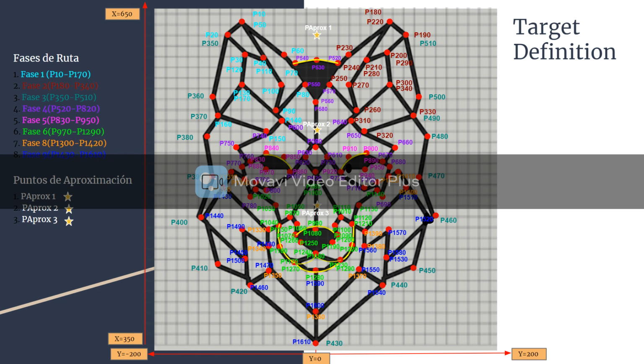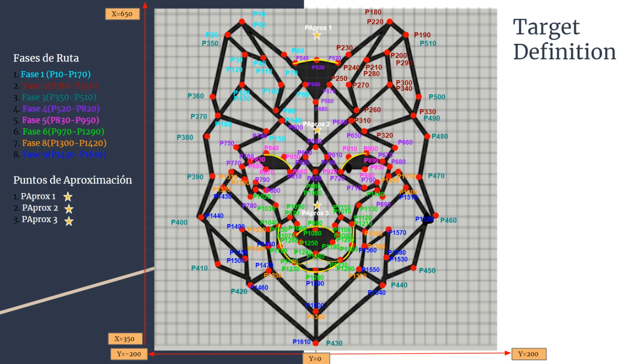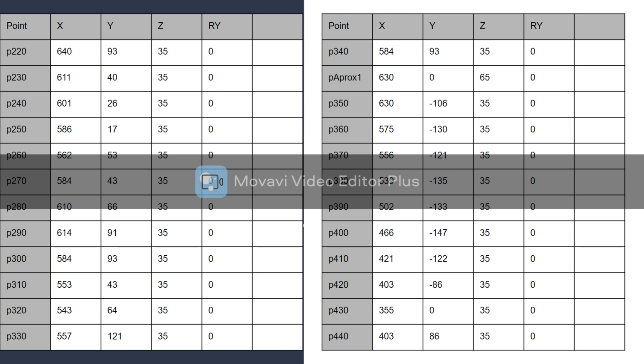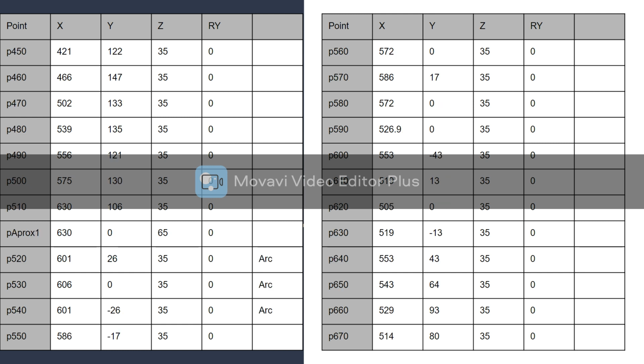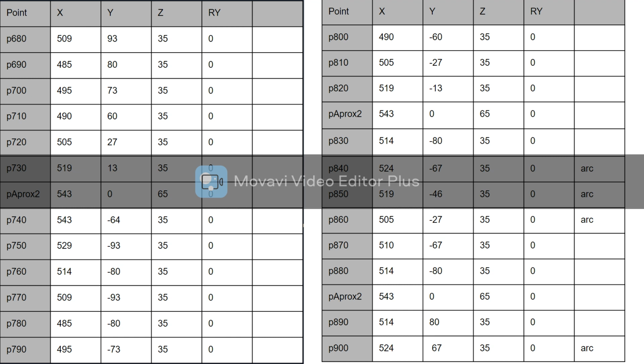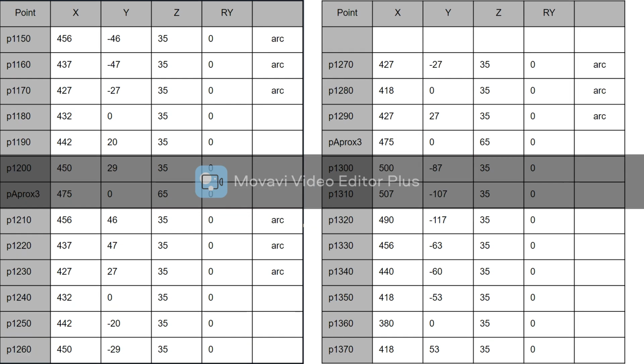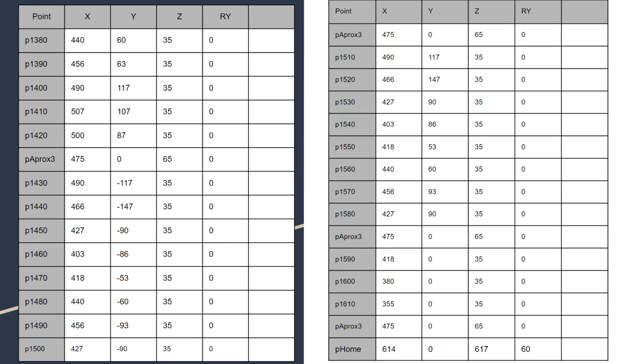We then distinguished each face with a different color and proceeded to adapt the coordinates that belong to each point. With the help of a square grid laid on top of the design, we assigned coordinates for each movement and made sure they made symmetrical sense as part of the drawing. After covering every face, we went over the trajectory and identified each point as a possible move L, move J, or move C movement that will later be transcribed to the programming aspect of the project.